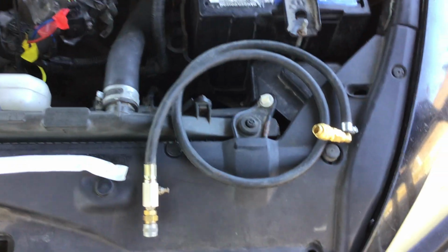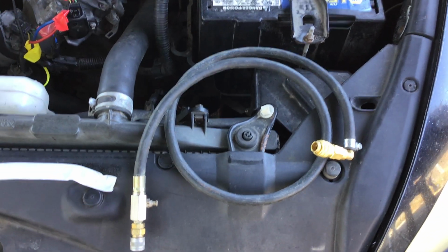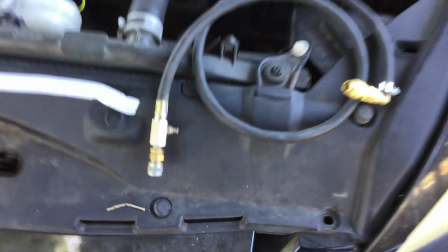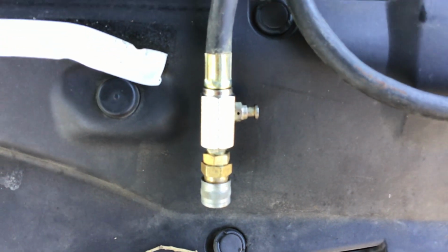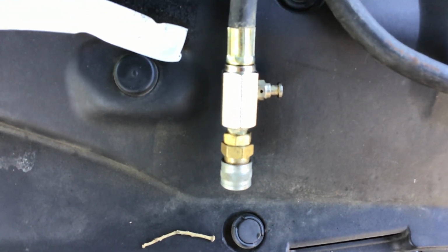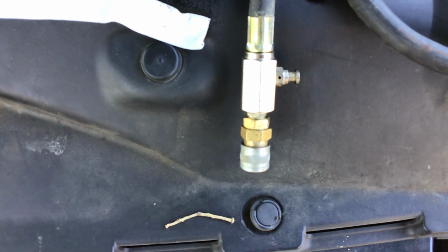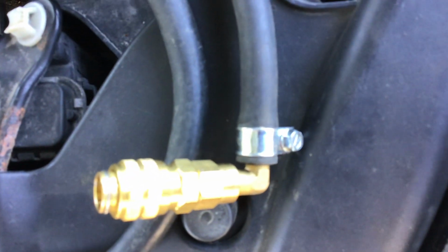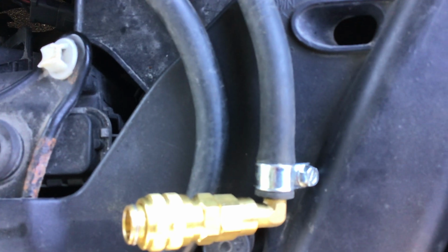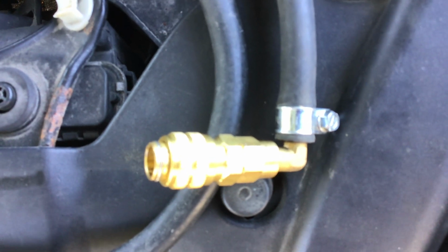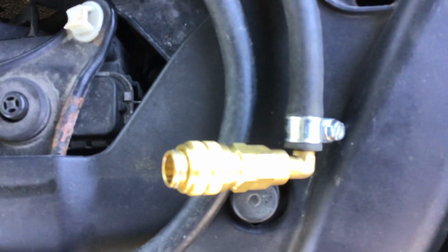I want to show you how I was able to get to the sending unit. I went to Amazon, and they sell automatic transmission pressure test kits for about $20. You get a bunch of adapters, and I took the actual analog gauge from there and put the Foster coupler in. The Foster coupler is threaded, I believe, 1/8 inch by 27 national pipe thread. It fit right in there. Use some Loctite or Teflon tape. This is the quick disconnect, and I cut that hose, put a clamp on it, and tightened the clamp onto an adapter that comes with the kit.